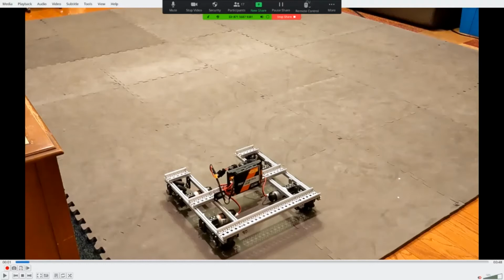Now, 7172, when they've done this model in the past, they would custom make plates to go on the ends to attach all of these together and make sure that they were parallel to each other where they needed to be parallel and perpendicular where they needed to be perpendicular. Since this last season, REV has come out with their channel structure, C channel and U channel, and so I decided I would prototype using the C channel and U channel, and I have to say it works really well for this particular purpose.